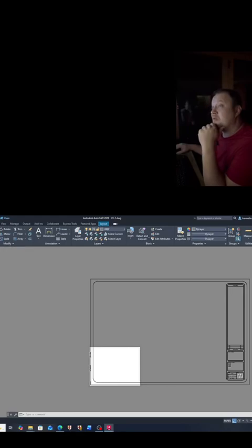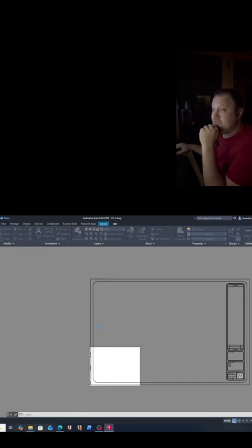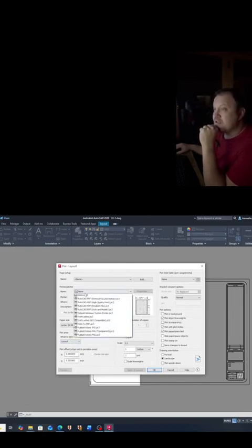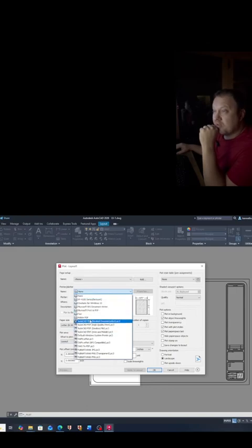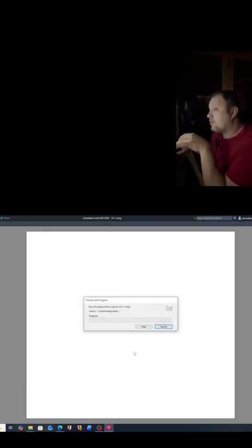So let's say that we wanted to print it as it was. Let me show this again. We're going to do single sheets. Right here, it's set up for 8.5 by 11. What to plot, the layout. If we were to just set this to Adobe PDF, usually there's a DWG to PDF, that's what I always select. Then I'm going to hit apply to layout just so it keeps that command. If we went to preview it, we're only getting the bottom left corner here.